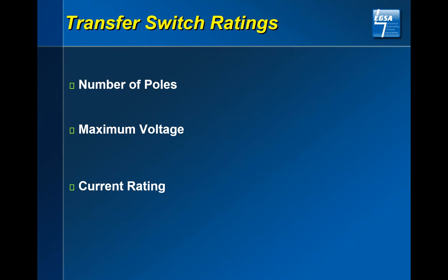I recently looked up the definition so that I'm not misstating it, but you can only carry 80% continuously. So if you're at a 600 amp breaker, I'm only supposed to carry continuously 480 amps through that circuit breaker. When you look at the definition of the circuit breaker, the period of time that you can draw the full 100%, the full rating, the 600 amps, is limited to about 3 hours or such.